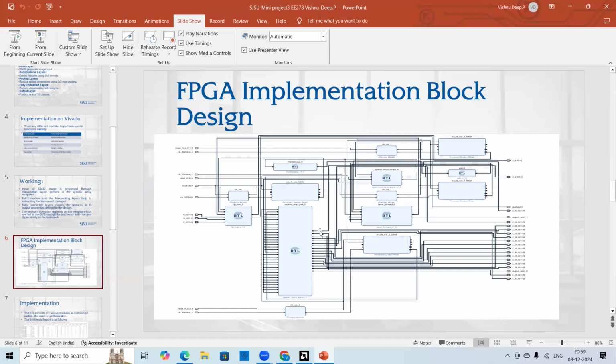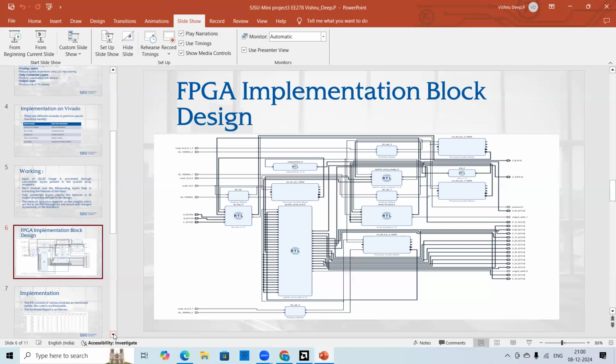The outputs of the systolic array are given out as pins here, and output valid is a flag which tells us about the validity of the given output. This is the pooling layer buffer that we are going to use. This is going to be attached in the Xilinx Vivado project, which I'm going to be updating.